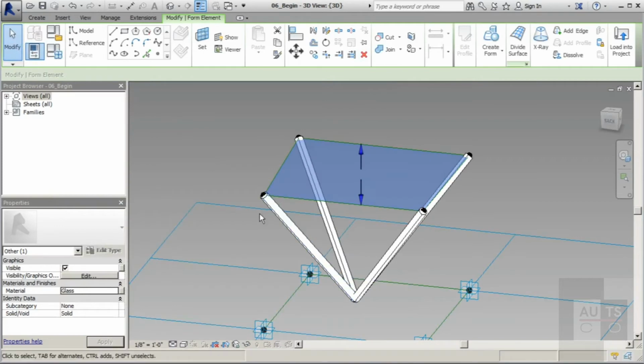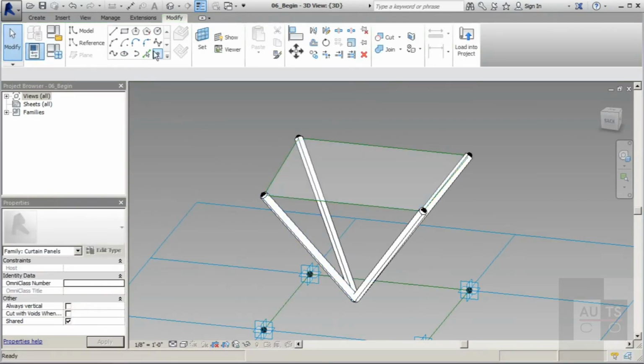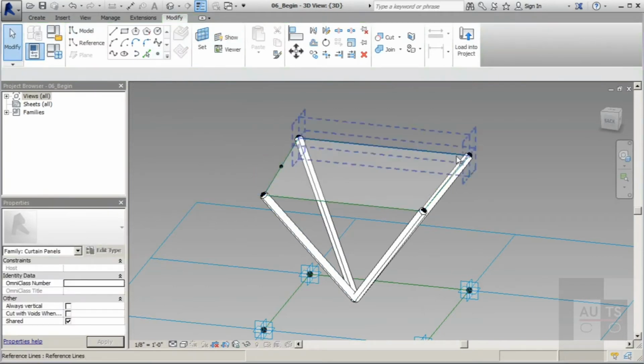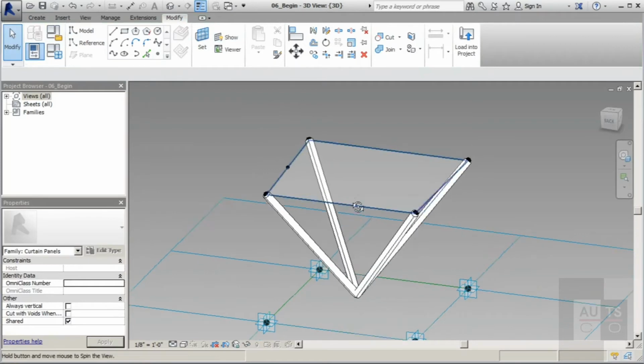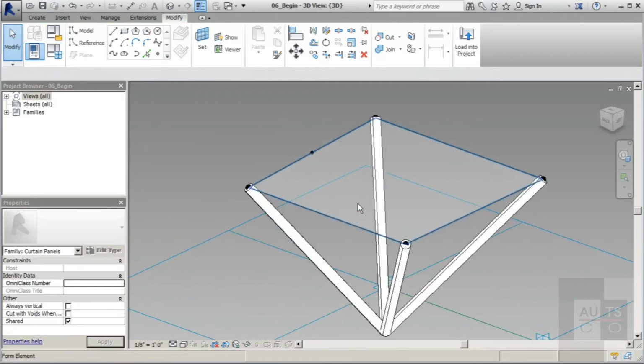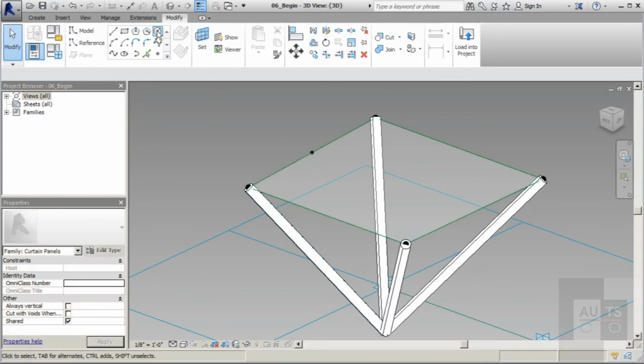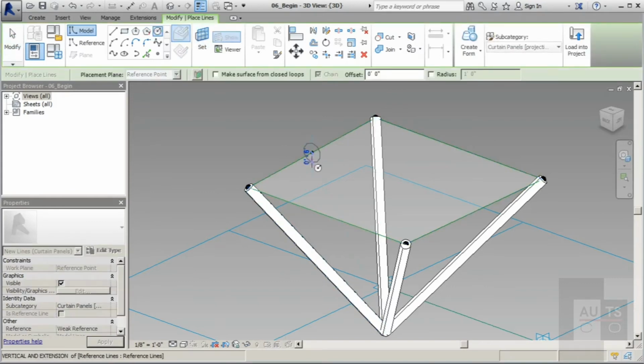I click OK here, and I'm also going to set a point to create our form for our framing that's actually going to house this in. And again, we're going to go with that same 3-inch dimension. So we're going to be consistent, and maybe these adjustments will actually allow our structure to be accepted by that form we've created. So this time I'm going to set there. We'll draw another circle, and we'll do 3 inches here as well. 3 inches, enter.